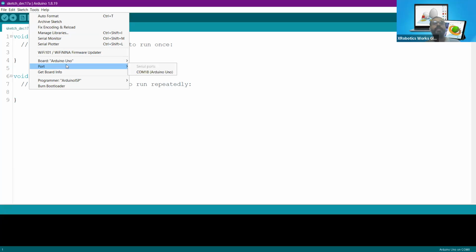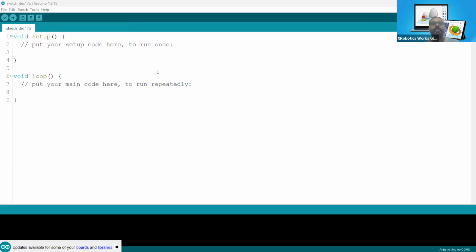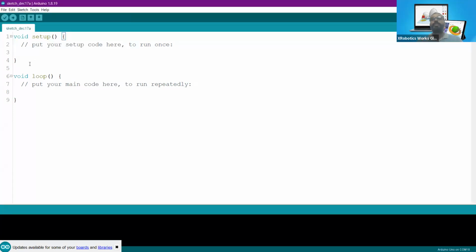The time when you plug in the microcontroller, the port option will be clearly visible to all of you. So I have to select COM port 18, that is the communication port. Now I'm ready to upload the program to my microcontroller, and you can see one of the LED blink programs which I already uploaded, helping this LED to blink, because this particular LED is the onboard LED.